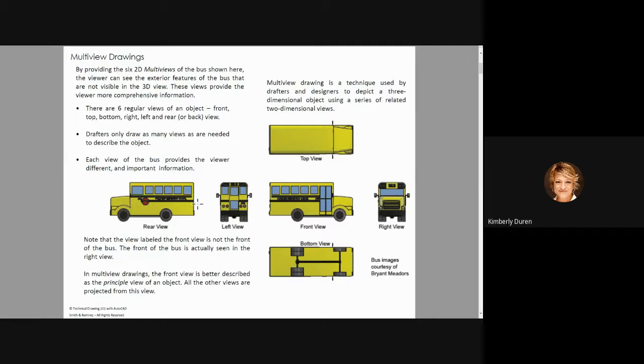So if I needed this back view or rear view of our primary, I would have to have the left view and then touch the left side of that, and it would rotate to show the back side of that. Likewise, I could do that on the right of the right view. I could do it over here too, and it would just be flipped in the other direction. And then the bottom view from the primary, I could get here.